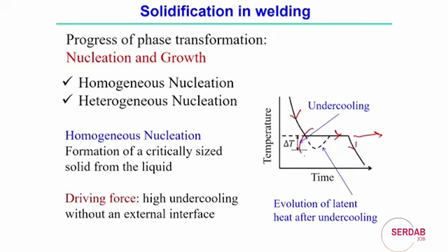So, this undercooling is the main driving force, and that undercooling is specifically responsible for the homogeneous nucleation process. That nucleation actually happens throughout the structure at a time. But of course, this undercooling is achieved at a very local position within the pool of liquid metal, at which point there is an undercooling. Several points can be undercooled locally, achieving some amount of undercooling, and once it achieves the undercooling, it starts the nucleation process. This type of nucleation process is mainly known as the homogeneous nucleation process.